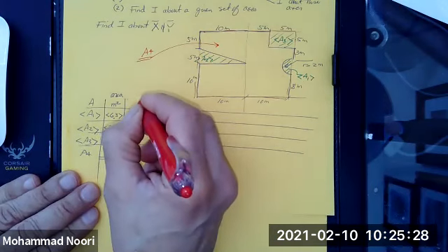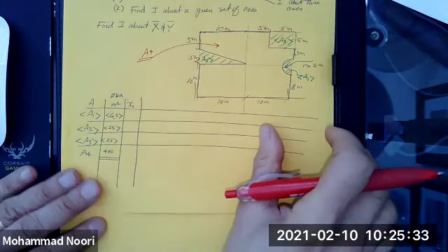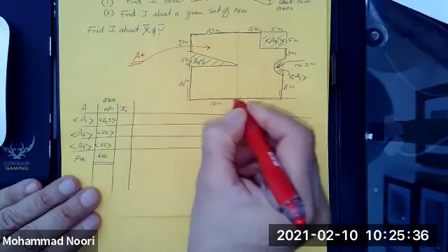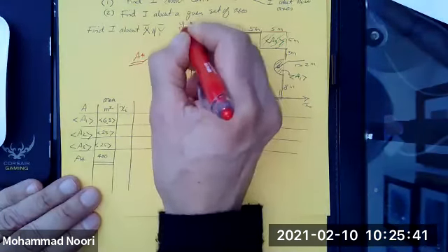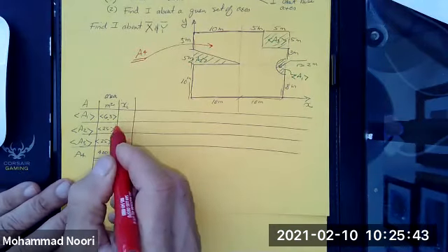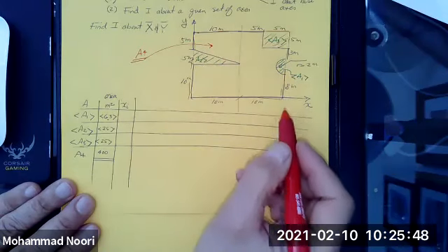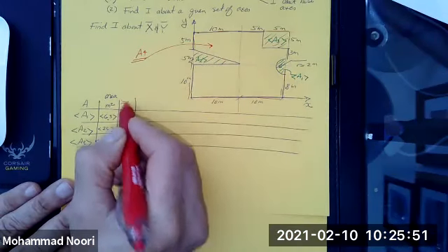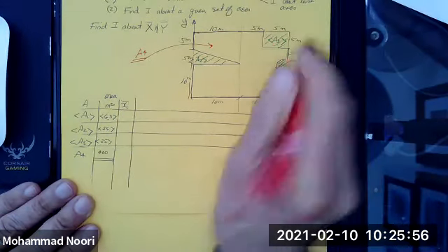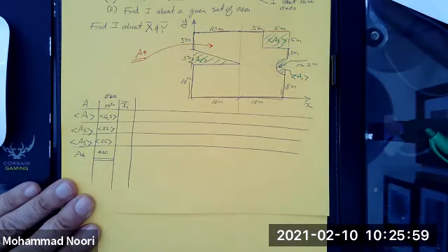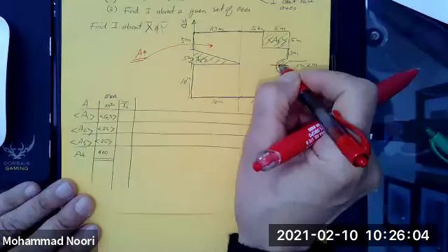So you remember the next column then would be xi. What is xi? Let's say you set up an x and y coordinate. With respect to those, you're measuring the centroidal distance from each shape to the x-axis and then the y-axis. For area 1, this is its centroid, right?